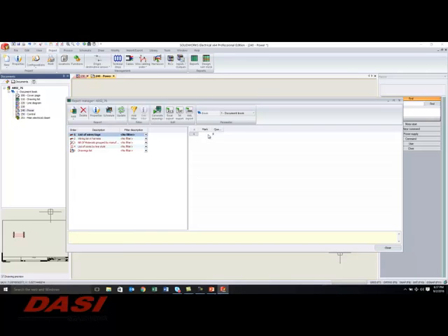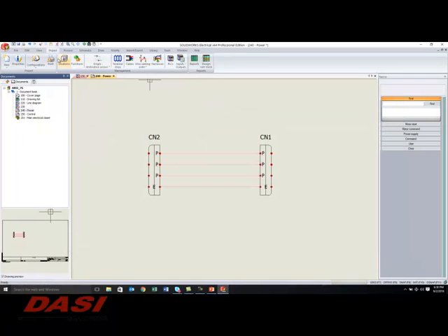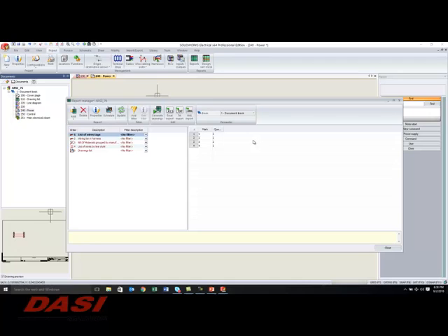Well, it looks like I have 8 wires or 8 spots with absolutely no tags to them right now. Obviously, I need to do some numbering. We'll do that real quick here, just so that I have something. We will do the process of numbering the new wires, which are those 4 wires there. As you see, it brought in those 4 wires. I go back into my report, Project report. And now you see I have 4 wires marked 1, 2, 3, and 4, and the quantity of 2. I can export that to an Excel spreadsheet now, print it out in a Brady labeler, and all of a sudden I have everything that my panel builder needs to actually start taping wires.